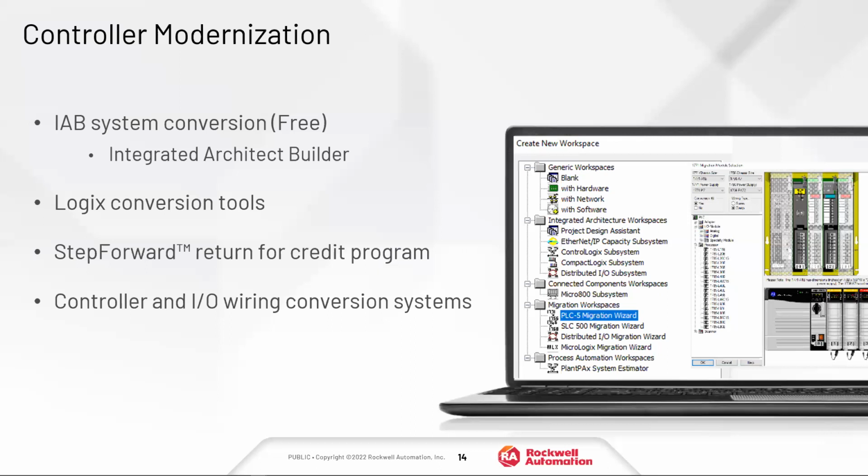And typically the most time consuming aspect of a modernization program, when you're actually on site converting it, is the wiring situation. So whether or not you have to lift and land field wiring to new hardware, if you don't have time for that, or if you don't want to do that, then Rockwell has created 2 different wiring conversion systems, one for a PLC5 conversion and one for a SLC conversion. And so we use those quite a bit. Over the years, we've probably done hundreds of PLC5 conversion systems.